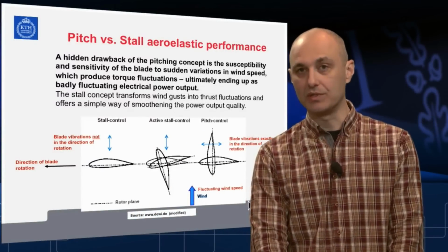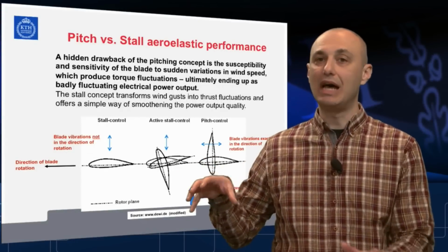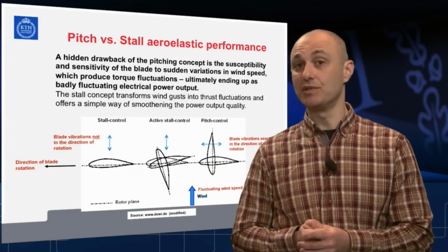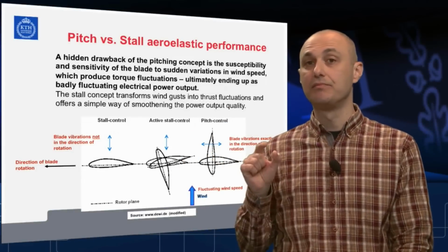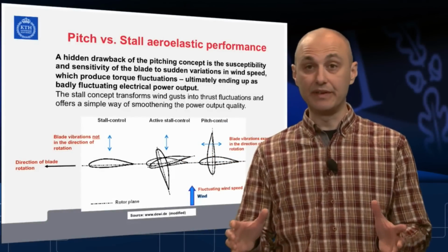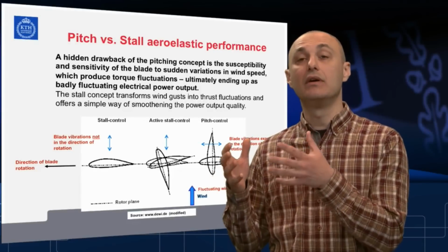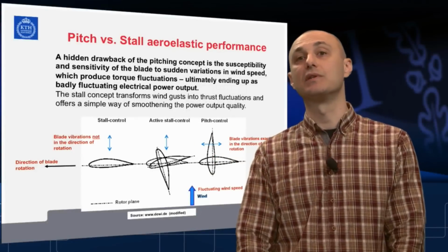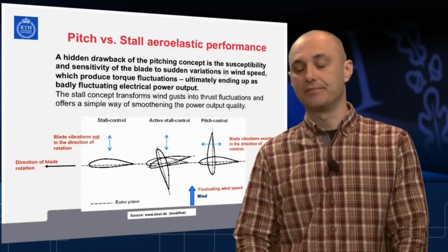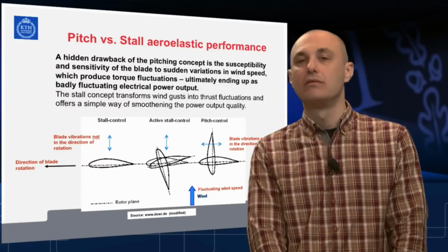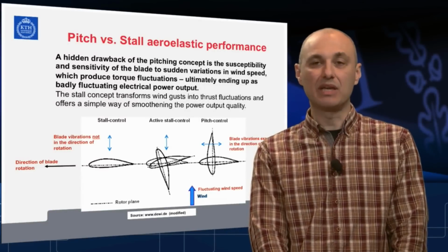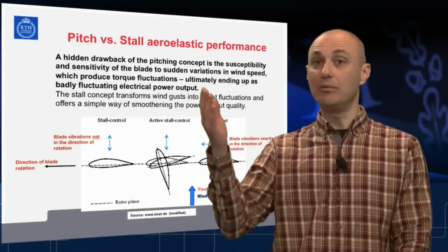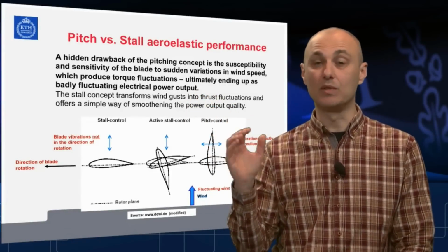With a pitch control, of course, you do not only need to have those mechanical arrangements so the blade can flip, you also need to have a proper control system where the feedback problem, and you remember what a feedback problem is in the control theory, you have actually to have a change so that you detect, send the signal before your control system manages to act. Pitch control, therefore, is always a bit slow, and you cannot make it quick enough. And if there is a constant variation in wind, your blade will start crazily flipping all the time.